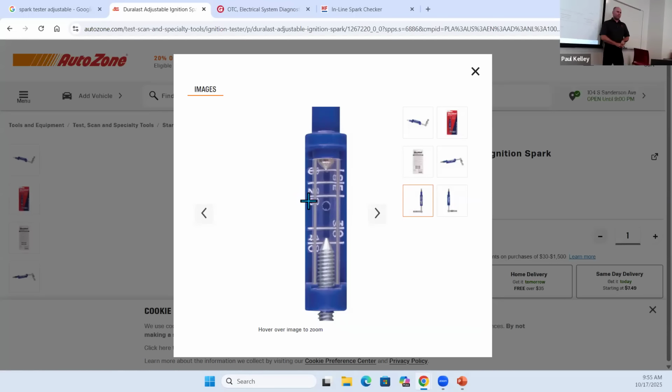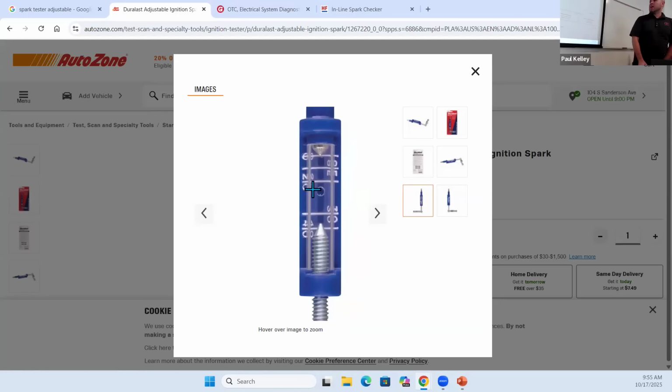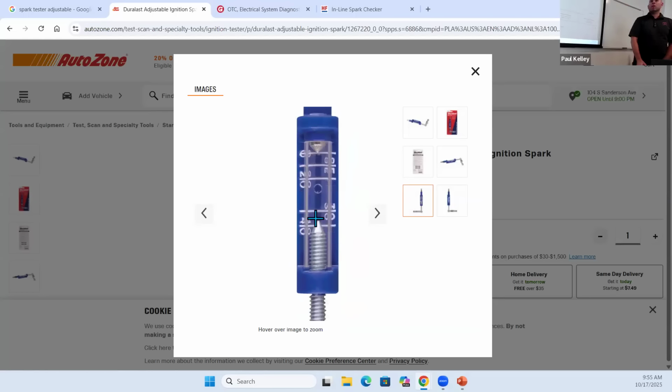There's a couple of points that are made a little bit later, but I'd like to point them out. Your spark plug gap is never going to be this big. So why would we test it that big? Well, I'll tell you. When the spark plug is in the cylinder and there's air-fuel ratio, depending on what the air-fuel ratio is, and also there's cylinder pressure, right?